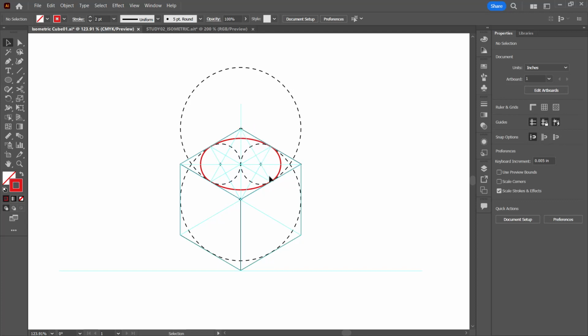But with that, we'd go here and do the same thing. From these two midpoints of our edges, we'd draw that arc. And then the same thing here. We'd start down at this corner and use this as our radius, thinking this would draw the whole circle. But then we would just go up to that same midpoint of that side to this edge and strike that arc, creating that ellipse, because those would run tangent to each other and meet up perfectly. So that's the theory behind it, and that's how you would do it.